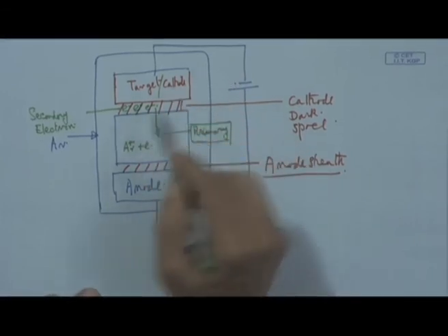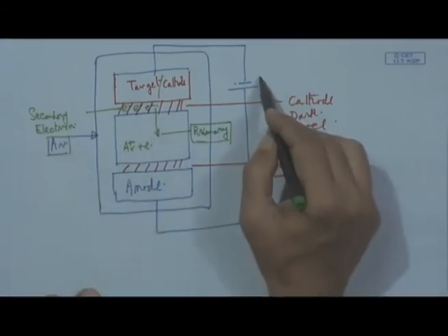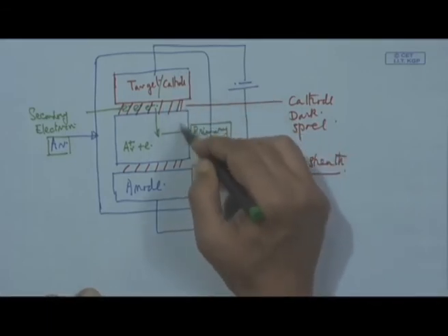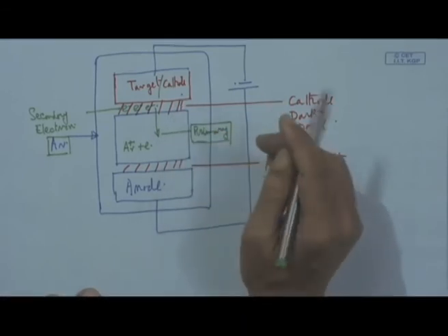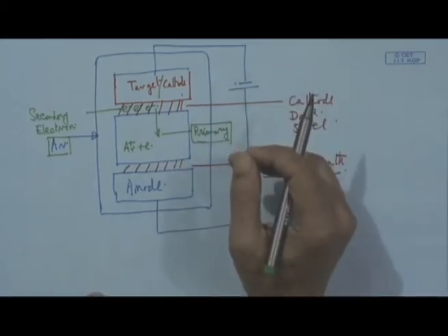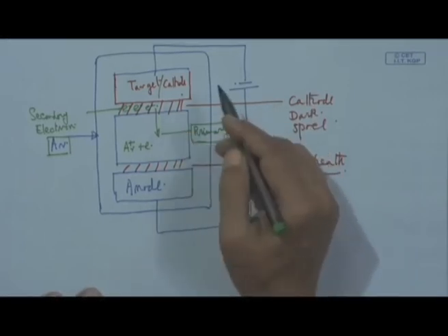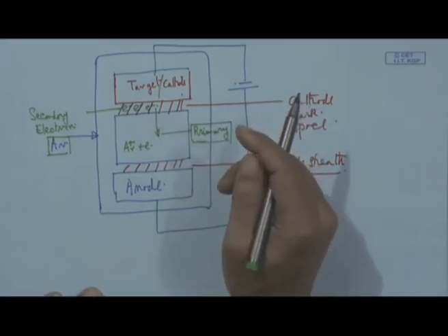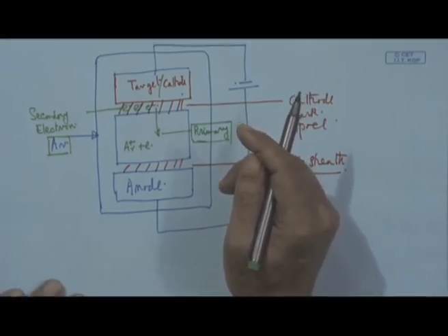In this, what is important is that the partial pressure of argon, this target voltage, this breakdown voltage, and this cathode-anode distance are put together, they have a combined effect, and accordingly we can see as the output the cathode current and also the deposition rate. So, this is what we know as very simple planar diode sputtering.